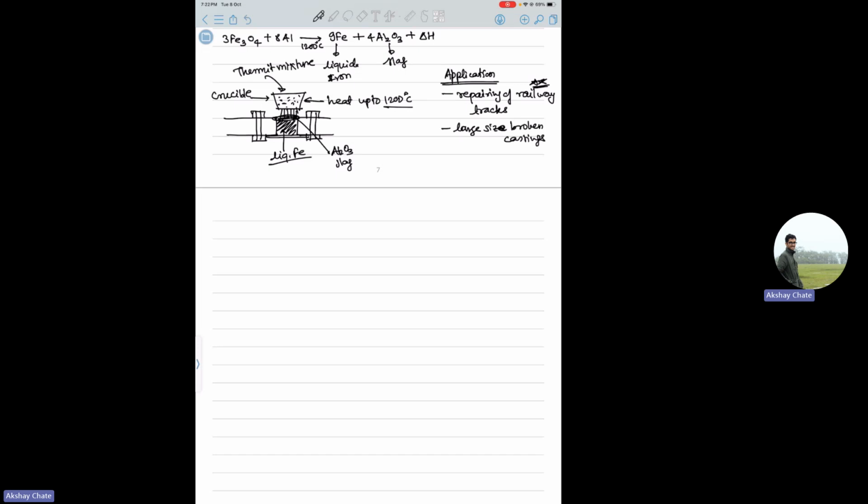But here you have to be careful that you apply very high current for a very small duration, so that heat gets generated and you have local melting. Then you press, which is called squeezing, done using presses or something like that. Then the solidification happens in this pressed state. So you get nugget formation, and in case of seam welding, you will have line welds.